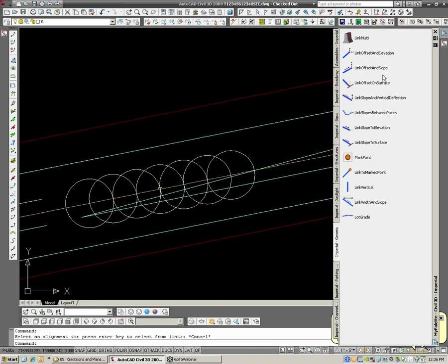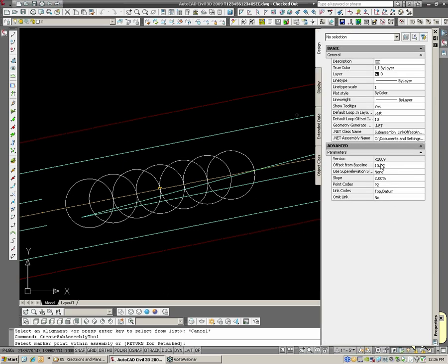That's why it's critical to use these assemblies up here, these offset ones, because these do not care if it's left or right. You can tell if you click on the assembly, see there's no left or right designation here. It's a positive offset or a negative offset. That's all the computer knows. It's sort of like our overlay and widening, positive offset or negative. So it doesn't know what's left or right. It just knows on the right side it's a positive, on the left side it's a negative offset, and it goes down and will cross back and forth across the center line. Great question.